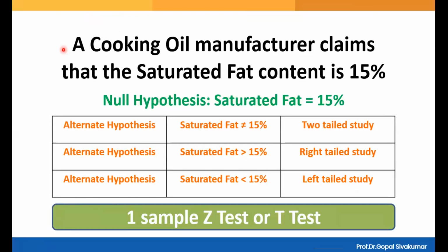If someone says to me that the temperature can highly affect our pouring process, then first of all it is the alternate hypothesis. So we can say that no, it can't be affected. After that, we find out the p-value. If it is less than 0.05, then we can reject. No, what is your statement? Temperature highly affects our pouring process. Temperature affects our process. That is first of all the alternate.